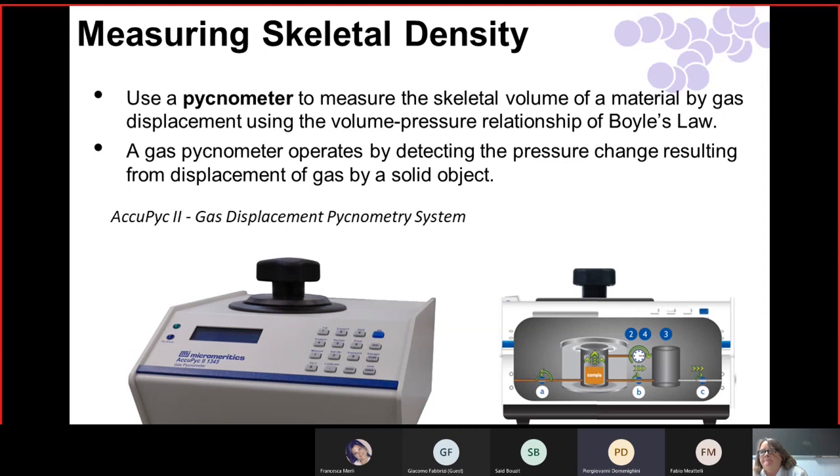Most of the silica we consider to be fairly homogeneous throughout, but depending on how you make it, you can see differences in density across an aerogel sample. Particularly when you make an aerogel in a container, like for the rapid supercritical extraction, we make it in a mold, and the supercritical fluid escapes from the top. Depending on how big that aerogel is, you could have density differences across the material.